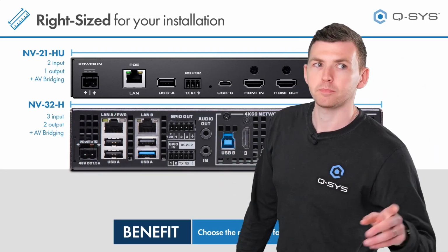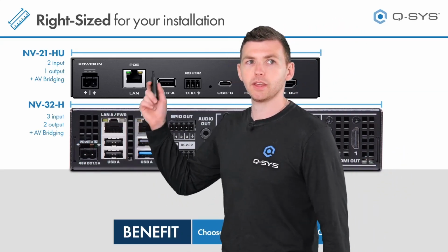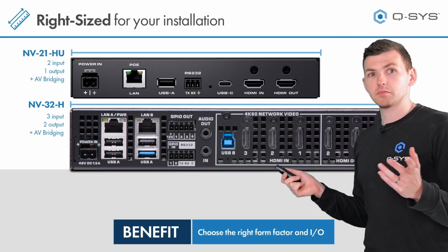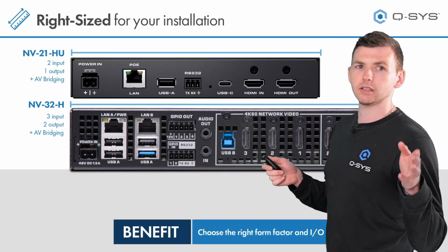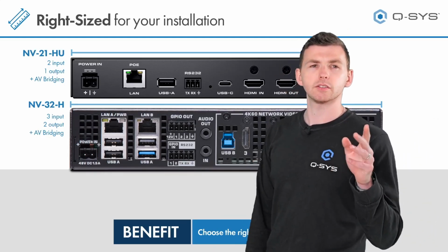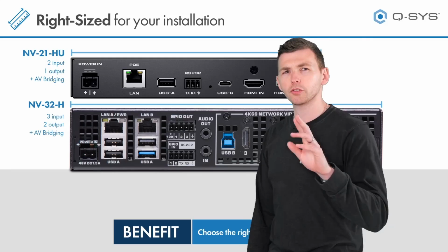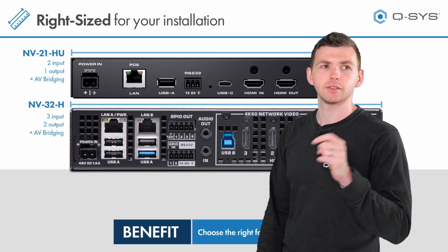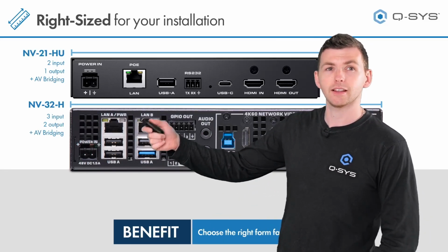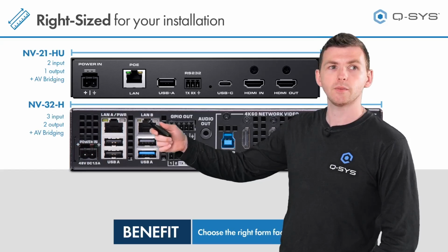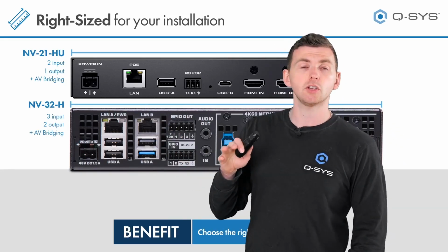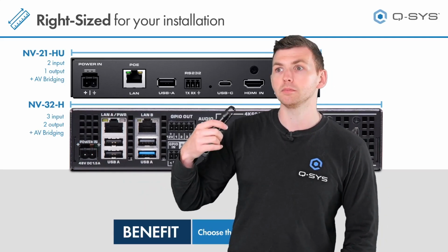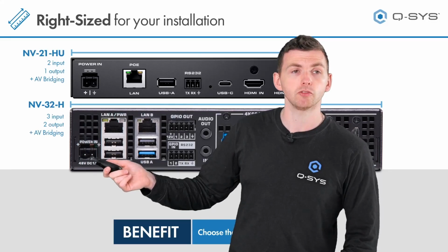Quick note on power. Both of these are PoE. Okay, PoE here, PoE there, but slight differences. All right, NV32, very, very powerful, lots going on. It requires the 90-watt PoE standard, which I think is Type 4. Okay, 802.3bt, I think. I know that because I looked at Wikipedia before this presentation. Now, that's cool, okay? A lot of the AV line switches, they all support that now. And if you don't have 90-watt PoE, no worries, because you can just use a 48-volt, 1.5 amp power supply, which you can get from pretty much anywhere, right?